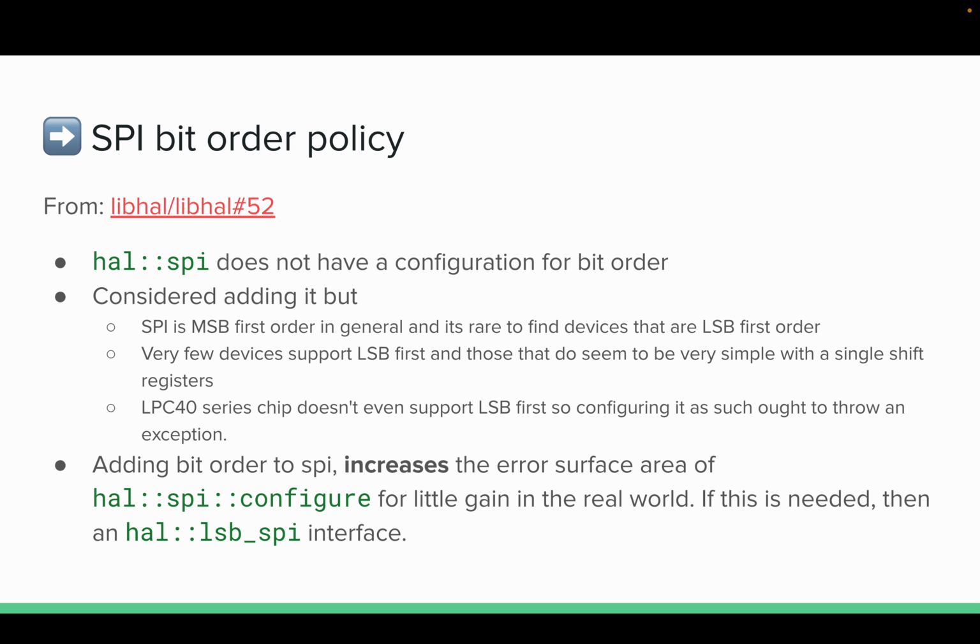And if you think, well, that's kind of slow, I'm like, yeah, cool, but also that's a bad design choice that chip made. Because it's so rare, not really a big deal. But if there ever is, for some reason in the real world, a reason to have an LSB SPI, I would just say make another interface.